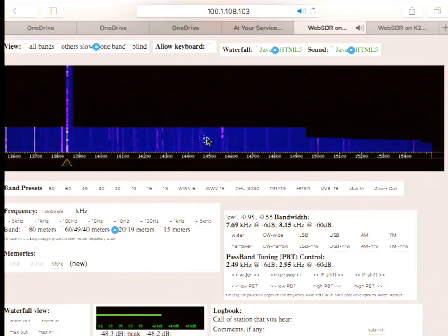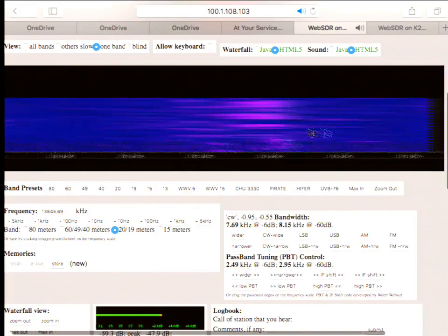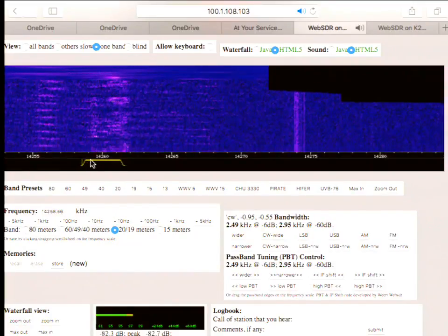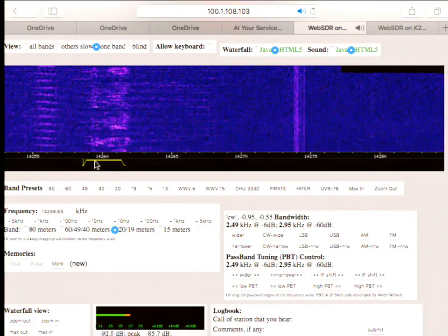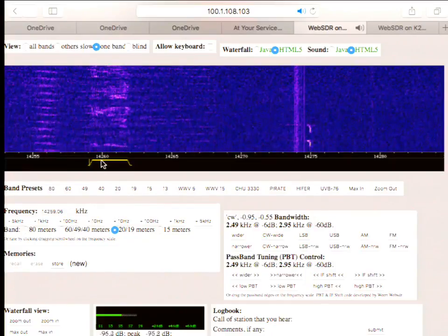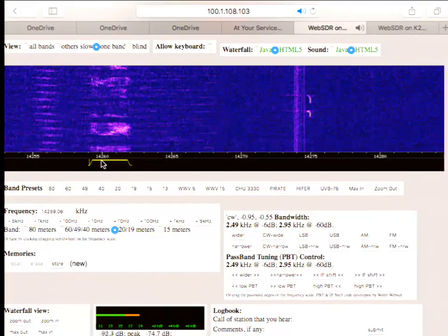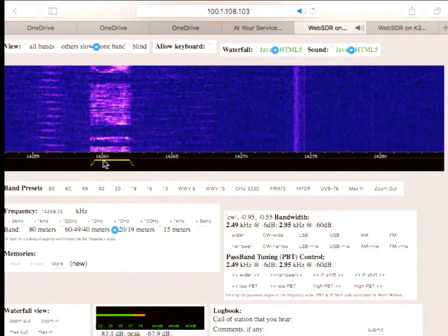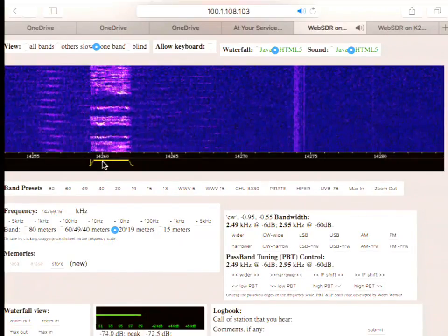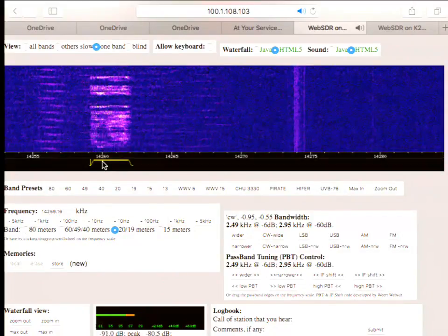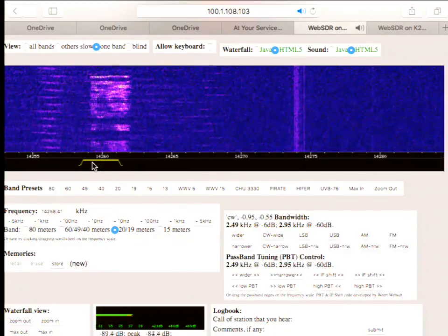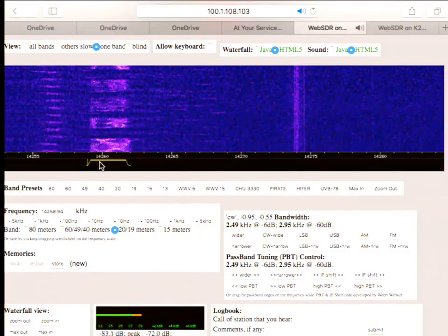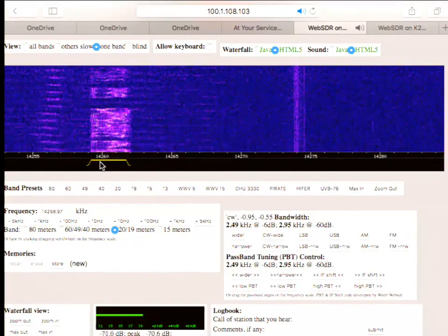Now I'm going to use a less robust one. I'm going to look at the amateur radio band. And this one over here, that's great. See the difference? Because what the demodulator really is doing is trying to replicate that to create what will be a real signal. And if I don't demodulate right, I'm going to get this kind of Donald Duck effect. Too high frequency. Too low frequency. Just right. Okay? All right, questions?